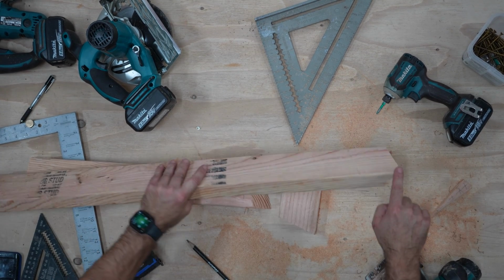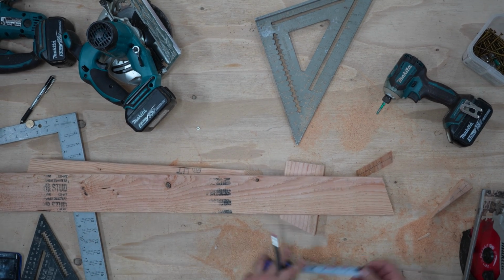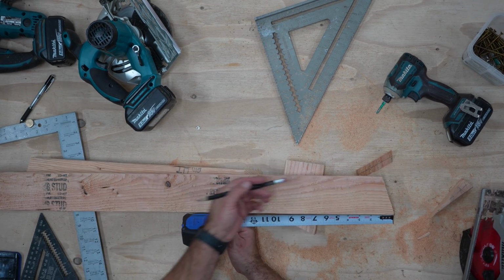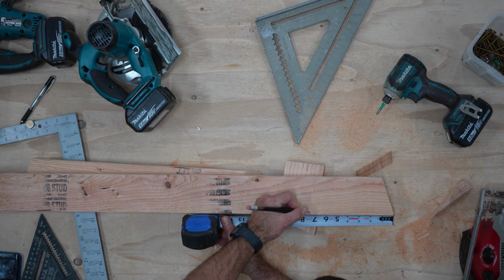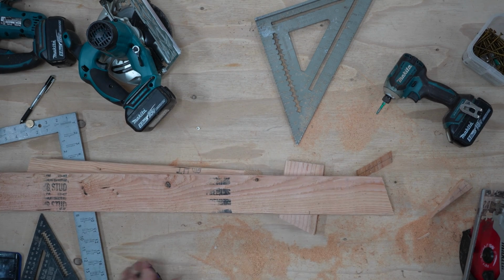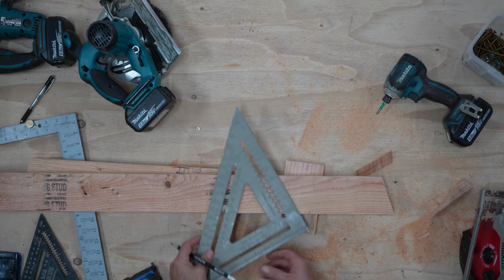Now I just need to lay out the jack the same way I would for a common rafter, which I covered in the last video. Notice how easy it is to hook my tape on the long point of the long point, which is often shortened and called the long. Any other point I would have to manually hold my tape measure in the right estimated spot.